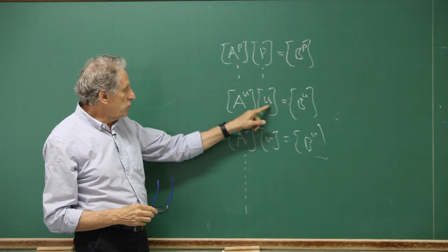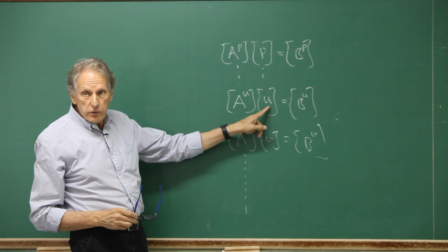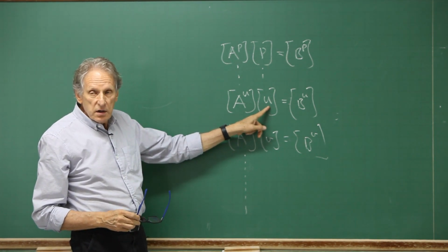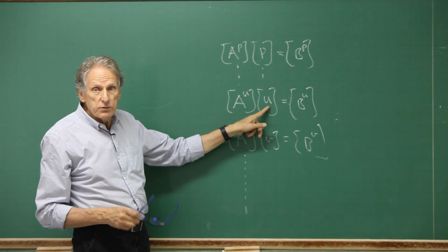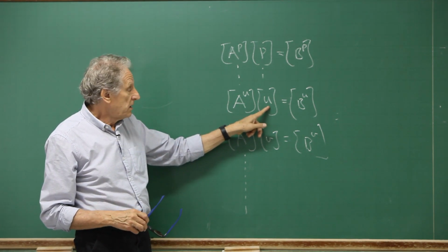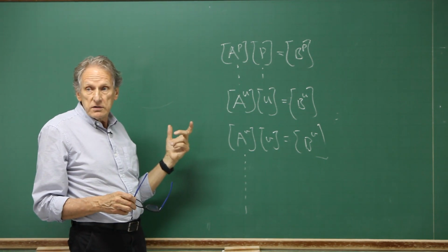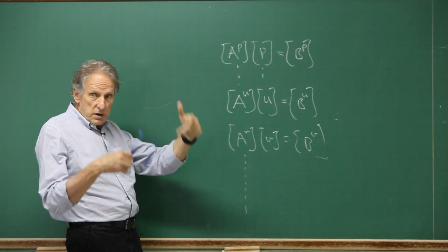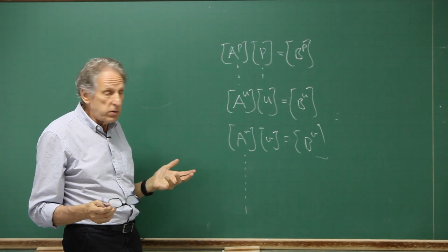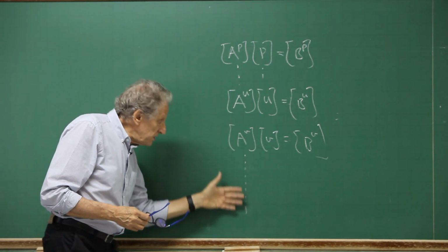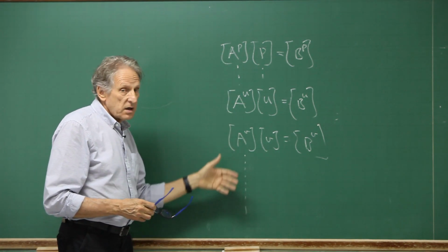Because when you are solving for the U velocity, where are the V velocity and W velocity which show up in the Navier-Stokes equation? They are in the coefficients. You have to change the coefficients. This is a non-linear problem. So when you do this iteration, you are iterating because of two reasons.